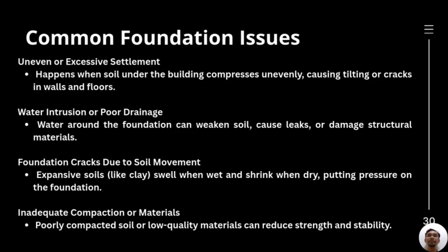Next is the foundation cracks due to soil movement. The expansive soil, like clay, swell when wet and shrink when dry, putting pressure on the foundation. Lastly is the inadequate compaction or materials. Poorly compacted soil or low quality materials can reduce the strength and stability.